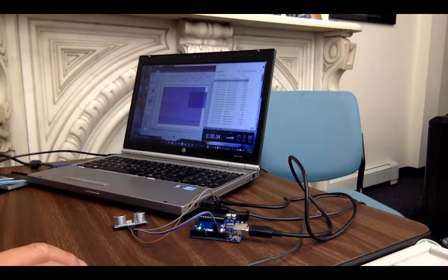After that, there is tools, and there is a serial monitor. Serial means we set up serial, right? Serial.begin, so baud rate is 9600, and Serial.println. I want to print out this text in the serial line. So let's see.